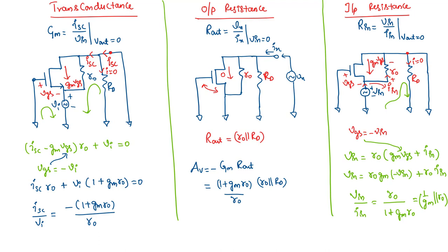We have seen this resistance expression for a MOSFET in diode connection. If you observe carefully here, the current flowing through RD is 0, which means we don't even consider that, and gate and drain terminals are grounded. Hence here the MOS transistor is actually in a diode connected fashion. Hence obviously by looking at it we could have written this expression straight away.